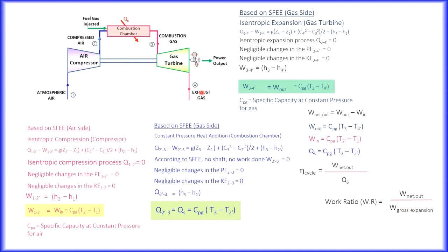When you look at the open gas turbine unit, the only part which gives you the gross is all the turbine work. If you have a series of turbines, you must add up all the turbine work to give the gross expansion. Remember, the compressor is compression, so it is excluded from this term. Any amount of compressors or any work in will be excluded.